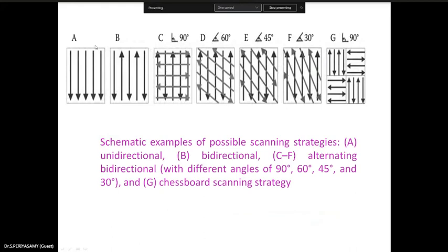Another possibility to improve wetting is the addition of certain alloying elements such as phosphorus in selective laser sintering of iron-based powder. So you can have additives like that. You can increase the wettability. That is what you can do. Here, this is normally encountered in SLS and SLM.